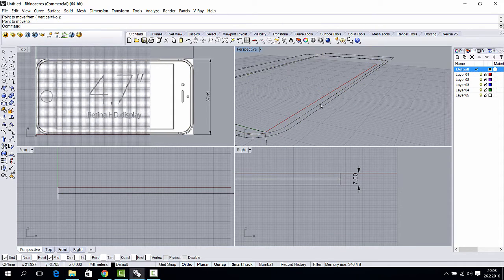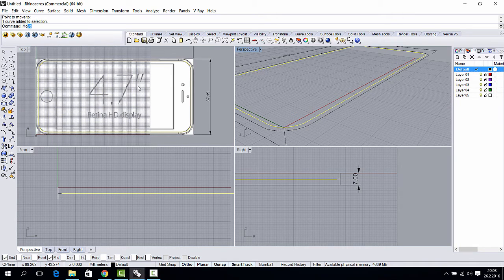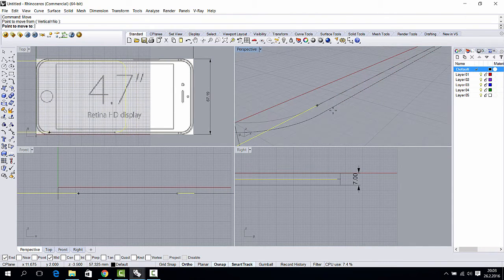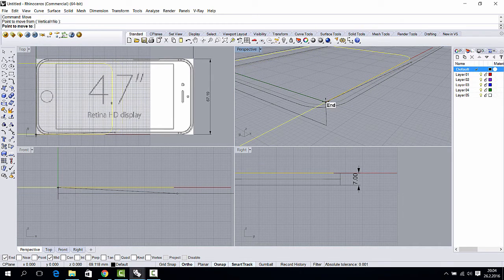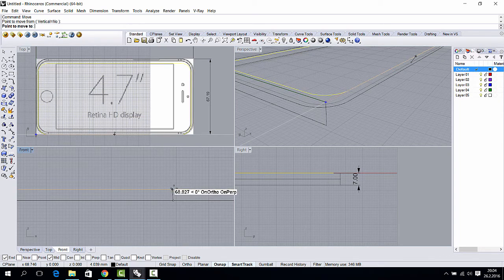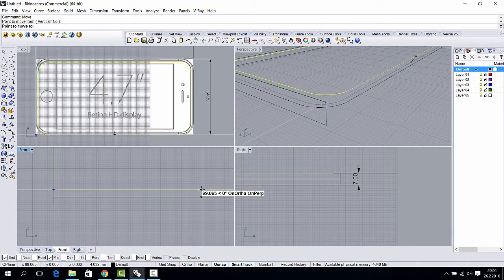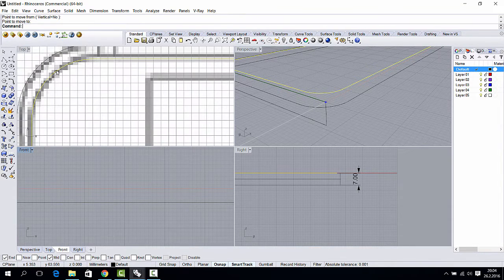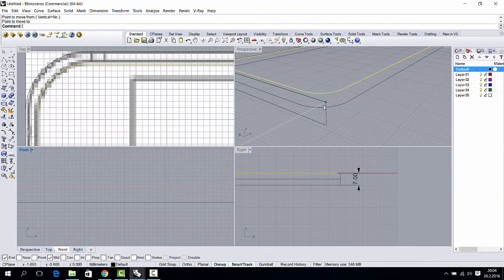So now select the inner line and select move, and then you have to see that you have the ortho on, and snap into the midpoint, and then with smart drag on, select the end point of the upper part, or the up corner I mean, the square's up corner, and then press shift and go up, and when it says int, press the left mouse button and you can see here up that it doesn't change the position from top view, it just goes up.